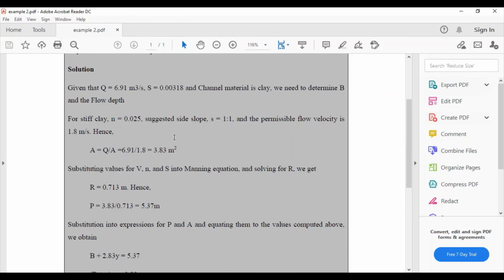So we have these parameters that we have checked from literature and others which we have seen from our survey. As we said, when we're designing an open channel, what we want is to find the depth and the width, and this can be found from the area. If we know the area, then this area is the height times the width, or the depth times the width.